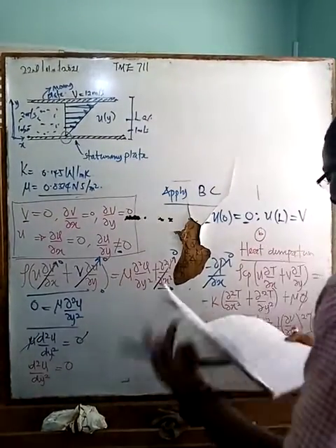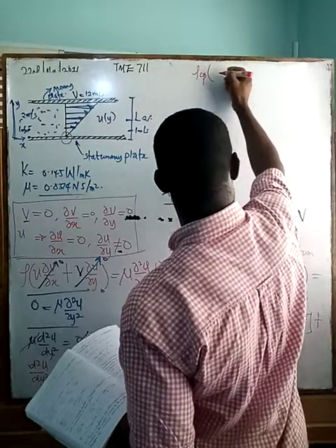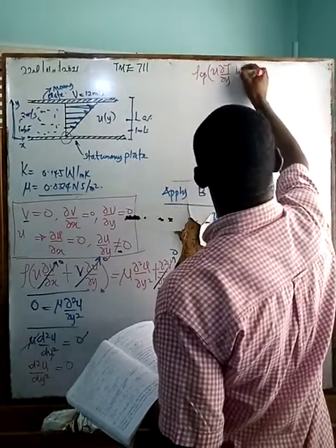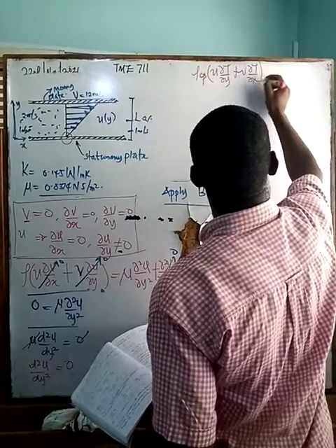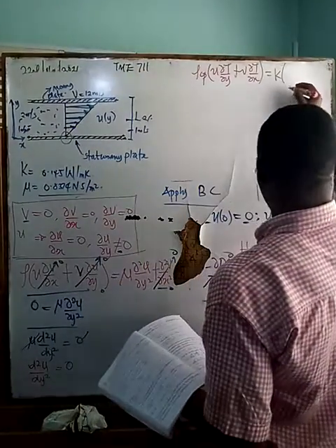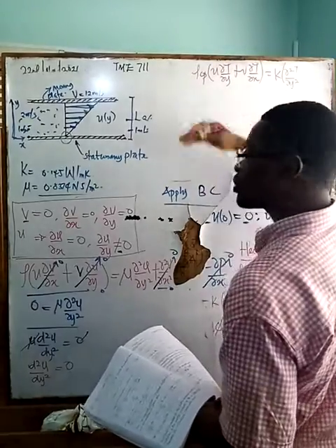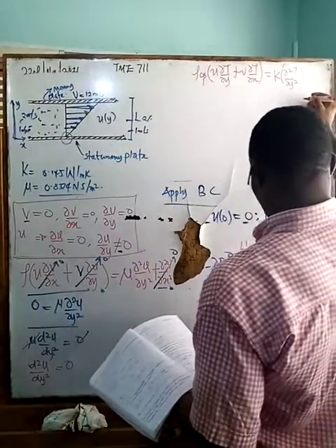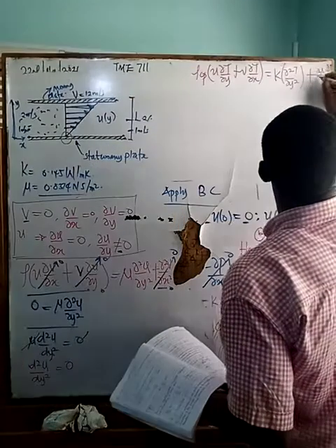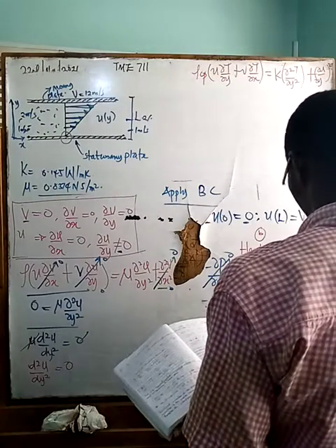So we only need rho Cp into u dT/dy plus v dT/dx equal to k into d square T over dy square, because the temperature is only changing along the y direction, plus mu du/dy square. Mu is missing there. Okay, mu.